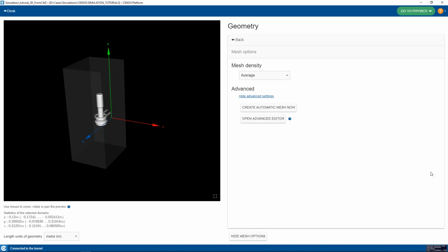There is, of course, the physical simulation part. For example, for 3D cases, if you are defining your workpiece with a full BH curve, not with a constant μ, then the calculation will take a longer time. But actually, at its basis, the element count is the only thing that matters if we are talking about the simulation time.